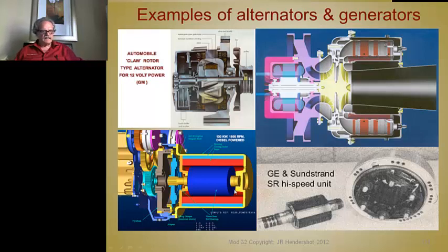This is a gearbox that's driven by some prime mover. Oh, I'm sorry, this one is diesel powered, it's not jet engine powered. It drove this gearbox, and there were actually two generators on this, a pair of generators. These are permanent magnet generators with their own bearings. These were surface mount machines, 4-pole machines, 120 to 130 kilowatts at 1800 RPM.